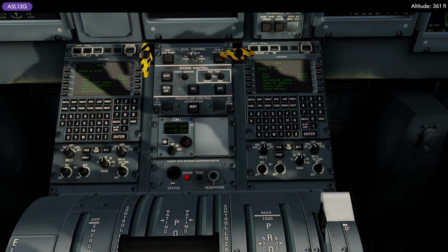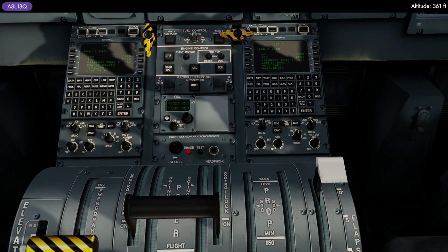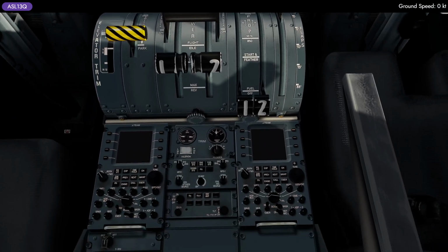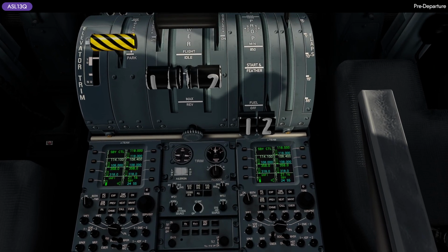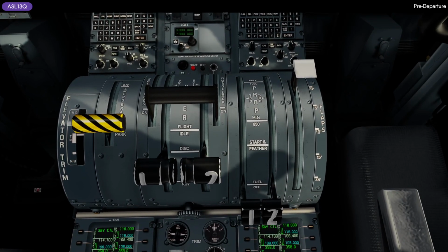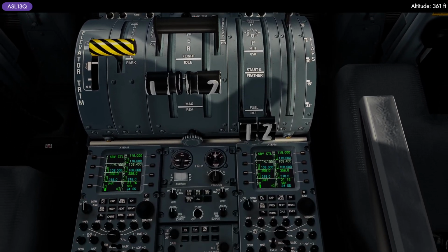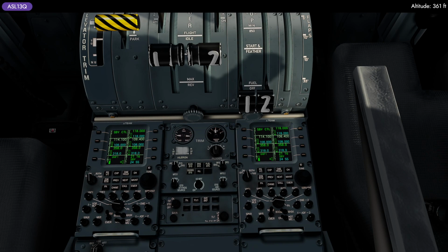So from here, we can actually switch our unit to test, go down here, where we'll turn on our radio panel, and basically, so if you hear that, test is good, so we can just turn it back to on position, and there you go. And now turn this on.